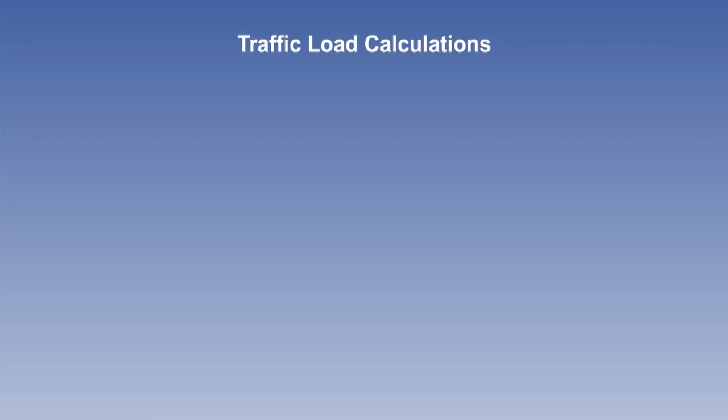A method of calculating the maximum traffic load that may be carried on a particular flight is to compare the available mass for that load within the restrictions imposed by the maximum takeoff mass, maximum landing mass, and maximum zero fuel mass.